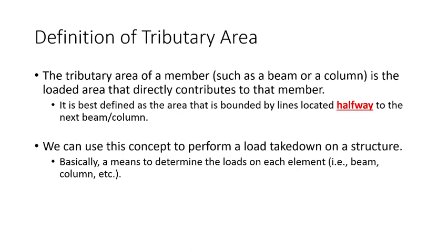So, for example, the slab systems that we're going to be considering today are what are going to be called one-way slabs. And so a one-way slab is one that is designed such that it only bends one way, right? So the idea is you've got beam, beam, beam, beam, beam, and you have slabs that bend like that, okay? Most building systems utilize one-way slabs.